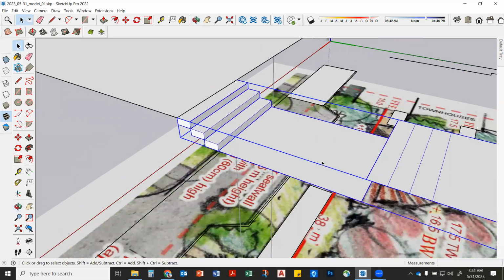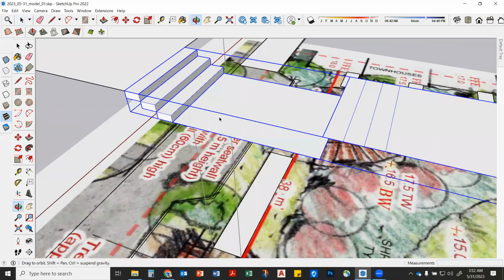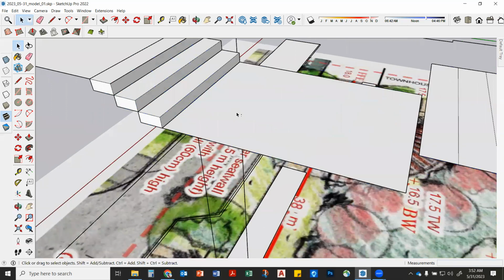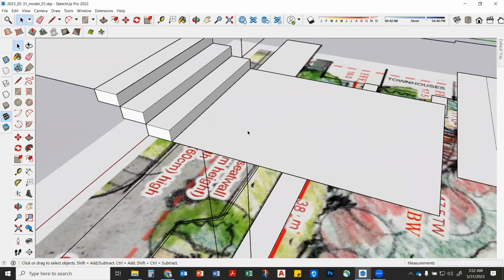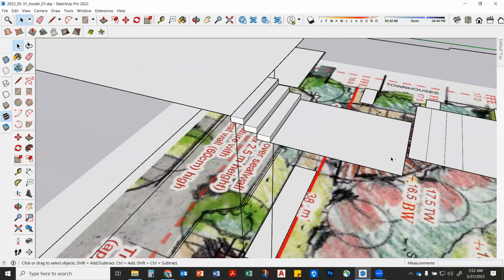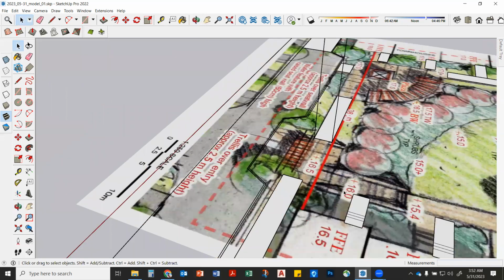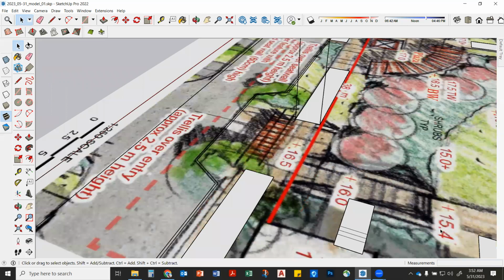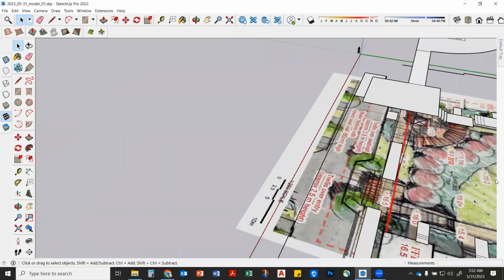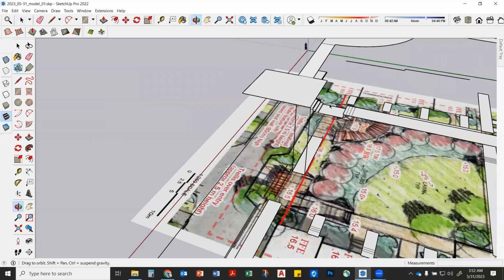We're gonna break for tea in a minute, but I want you all to get your stairs in there, yeah? That is your goal. So watch, if you're here with your stairs, we need another set of stairs down here. We calculated it. We looked at 16 down to 15.4, it's 0.6. 4 risers, right? If they're 0.15 each, yes? Okay. So we need 4 risers.